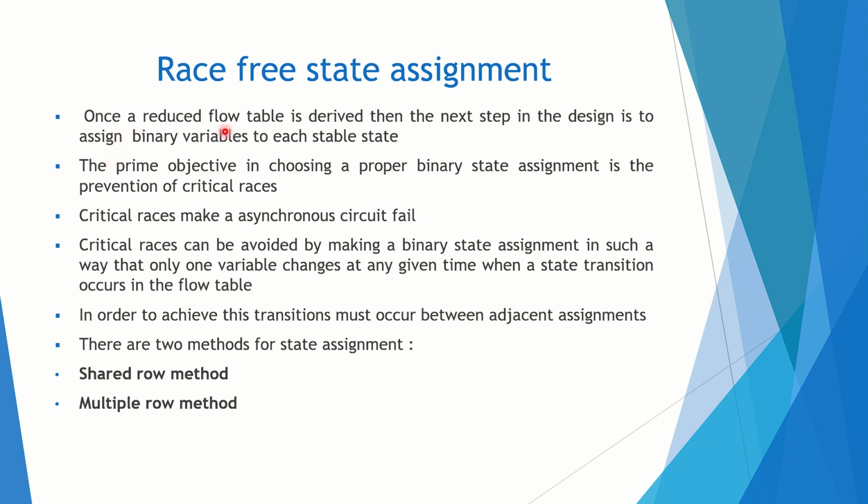Once a reduced flow table is derived, the next step in the design is to assign binary variables to each stable state. The prime objective in choosing a proper binary state assignment is the prevention of critical races.